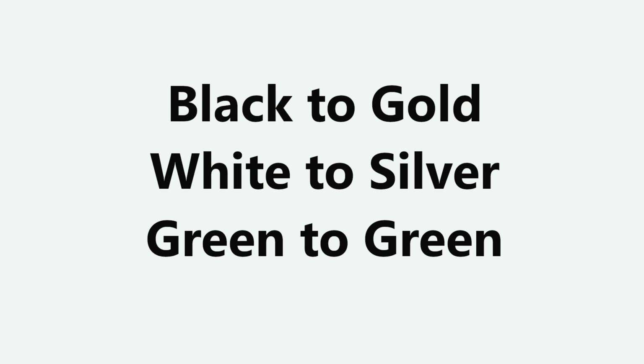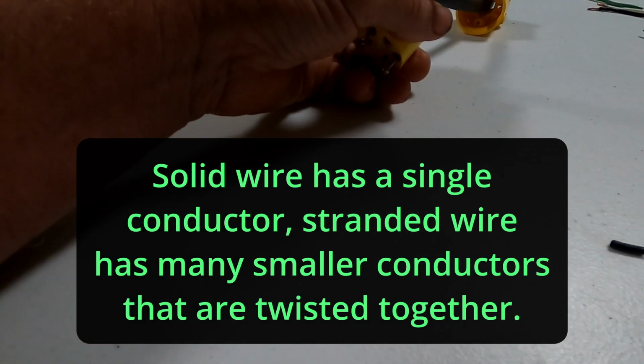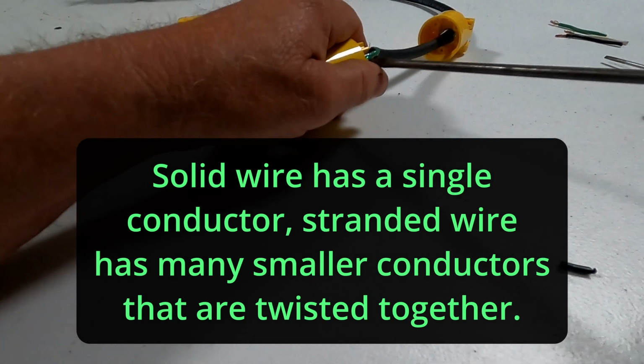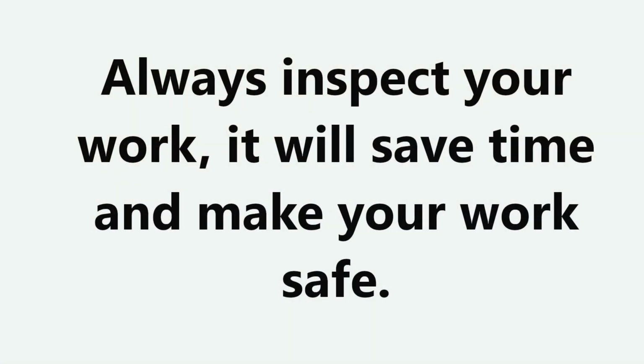Now I'm using 16-3 rubber cord, which means there are 3 number 16 wires. They are stranded, not solid. You need the stranded wire because you need the flexibility in a drop cord. Now we're going to check and make sure there are no wires hanging out. We're going to check each one to make sure it's good and tight.